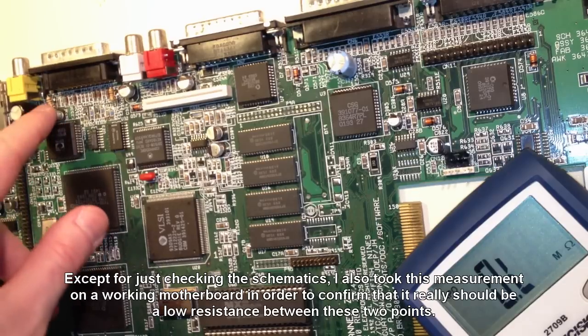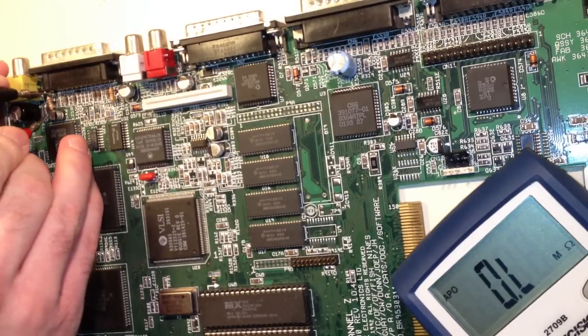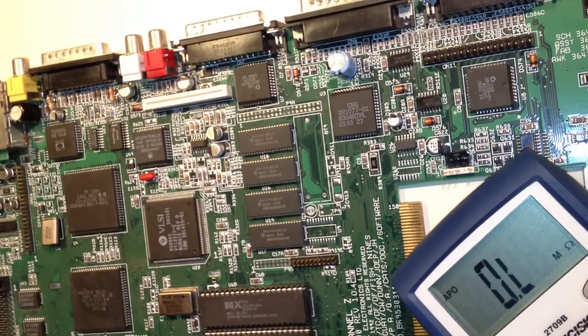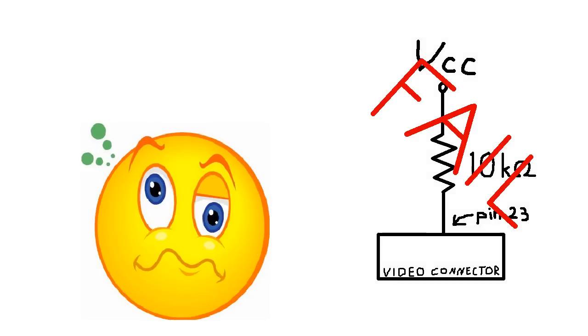I bet it's this resistor there, this through-hole resistor that someone put in there. I'm gonna check that one. I bet it's that one. Yeah, 9.82 kilo ohms. It's that one, alright. Oh, what are people doing to their Amiga motherboards? Seriously. Someone must have been thinking, yeah, I know, let's take a 10 kilo ohms resistor and put it between VCC and pin 23 of the video connector, because if I do that, then my Amiga motherboard will work so much better.